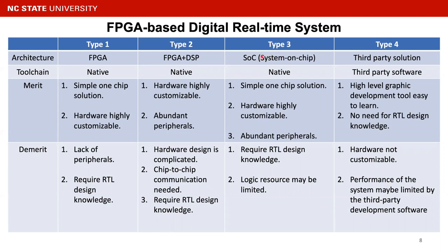Thirdly, we have the system on chip architecture, which provides a simple one-chip solution with highly customizable hardware. Also, it can include abundant peripherals. This platform also requires register transfer level design knowledge, and the logic resources on chip may be limited when compared with the first two architectures.